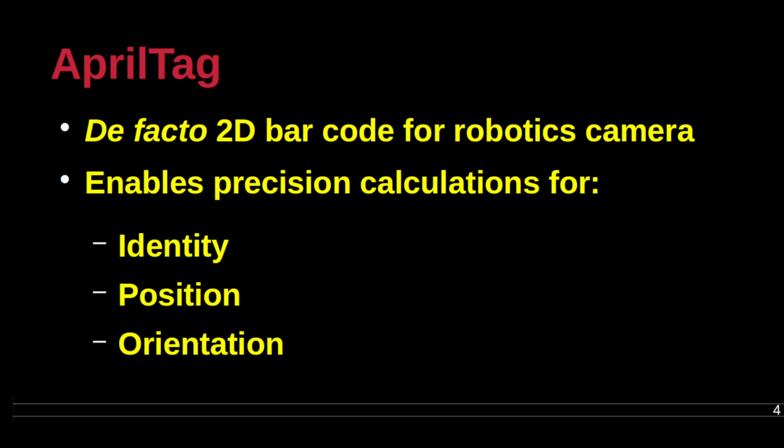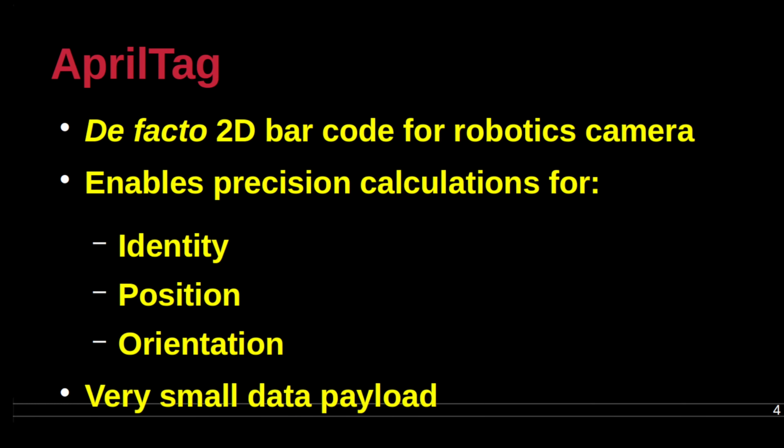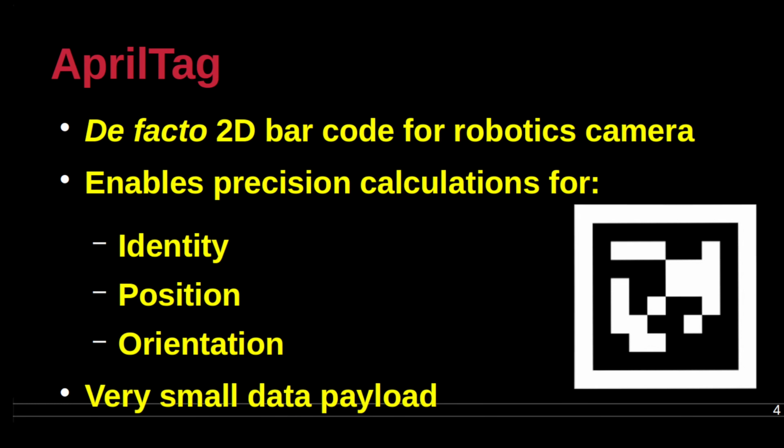The accuracy of the results is predicated by the calibration settings of the camera lens. FTC has published calibration coefficients for Logitech and Microsoft webcams. The supporting SDK has references to calibration techniques applicable to other cameras. If the webcam calibration has not been published by FTC, then it is very important to determine the coefficients with low error estimates.